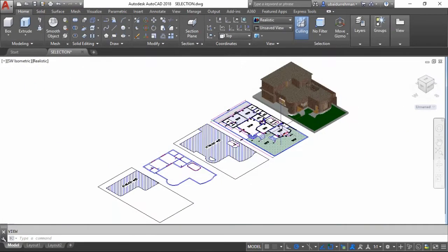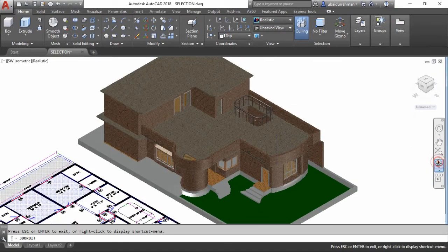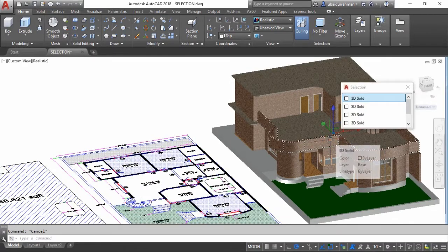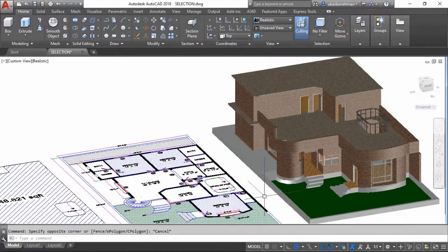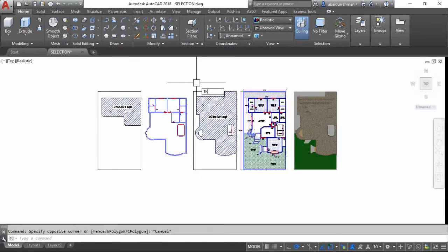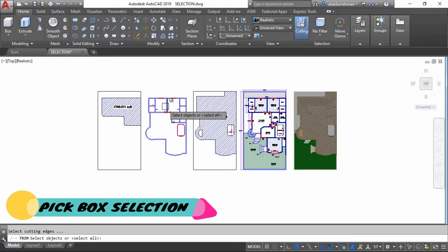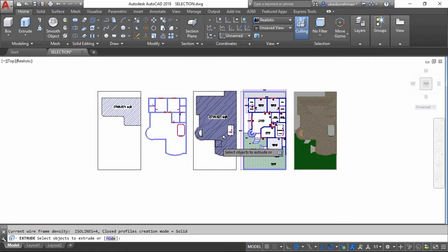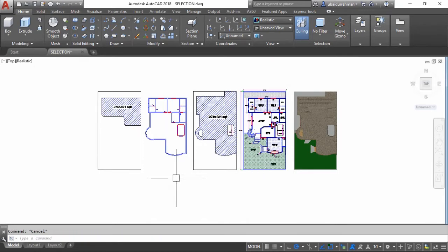If we briefly explain, it's all about clicking or holding the left button, and deciding the direction of selection, which makes four types of lasso selection. These are the most handy, convenient and suitable methods. In some cases, you have to select an object after starting a command. This can be noticed in many commands like trim, extrude, press pull and a lot of other commands. In those commands, our crosshair disappears, and only a rectangular shaped box appears for selection. This is called the pick box.